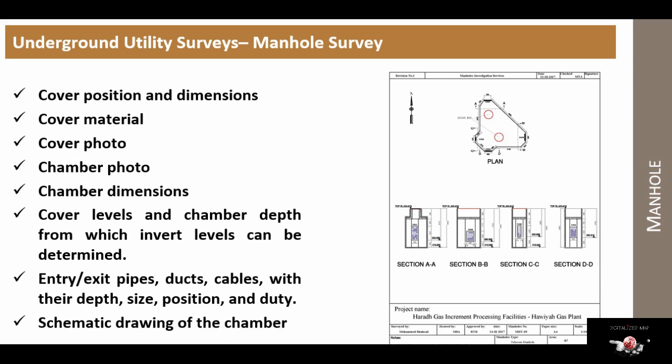Underground utility surveys, manhole survey: cover position and dimensions, cover material, cover photo, chamber dimensions, cover levels and chamber depth from which invert levels can be determined. Entry, exit pipes, ducts, cables with their depth, size, position, and duty. Schematic drawing of the chamber.